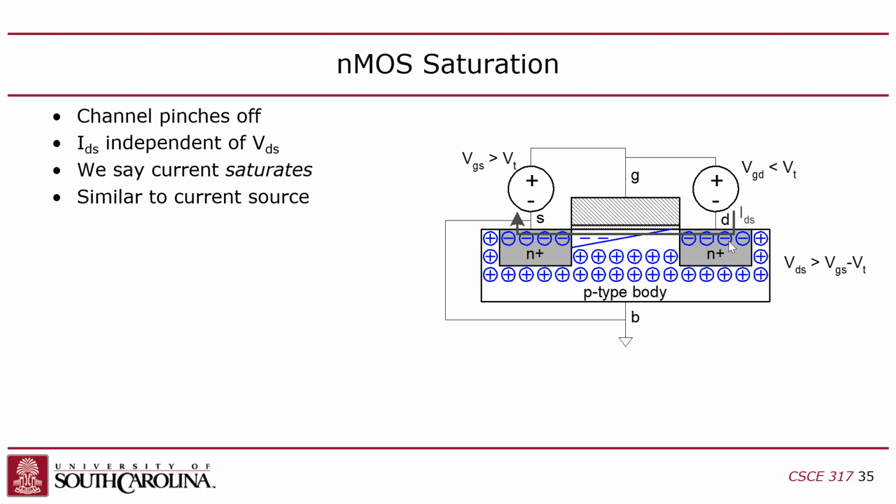So the problem is that transistors are inherently nonlinear, because whenever you're modeling them, you have to consider these three operating regions. There's cutoff, where there's basically no connection between source and drain. There's linear mode, which acts like a resistor until you ask too much of it. You ask it to source too much current, at which point it'll go into saturation mode and keep giving you whatever the max current was, but it'll peter out. So you can keep increasing the voltage over the transistor, but it won't provide any more current.